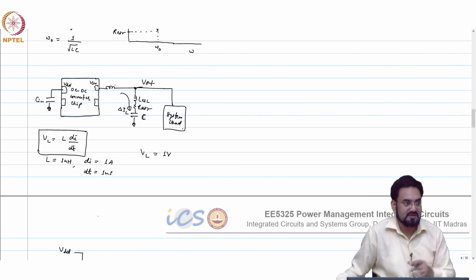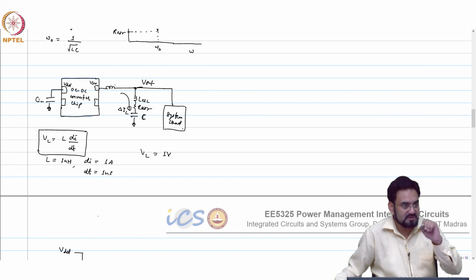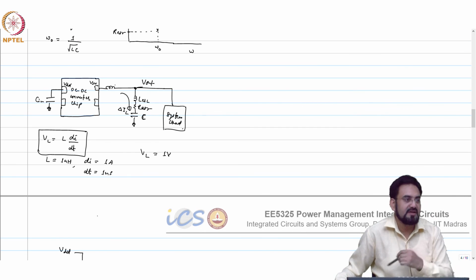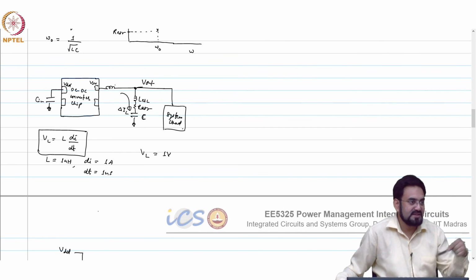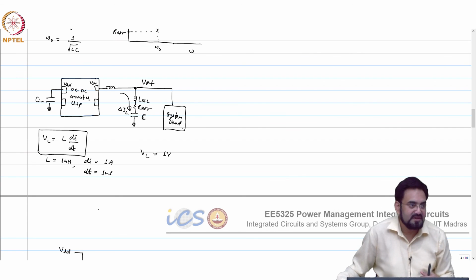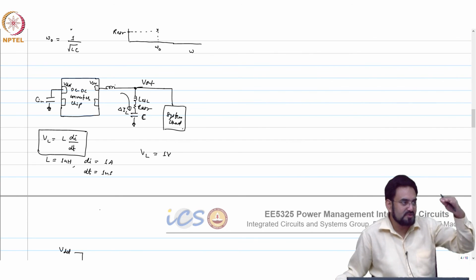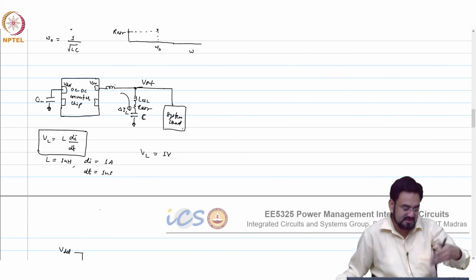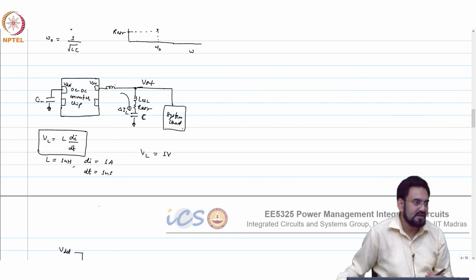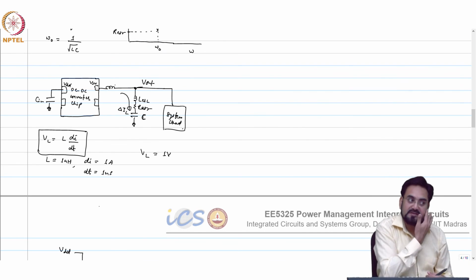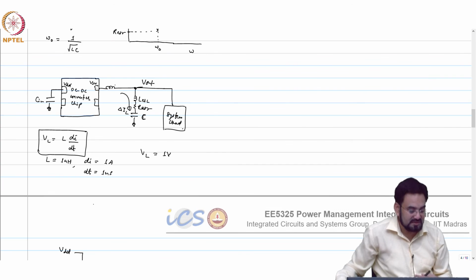When you are placing your FETs, you have to make sure that when you are routing those FETs and connecting to the ground, that should not have an inductance, because series inductance in that path will be in series with the source of your bottom FET, and then at the source you will again see this L di by dt noise, and that may again damage that FET. So you have to care about that as well.